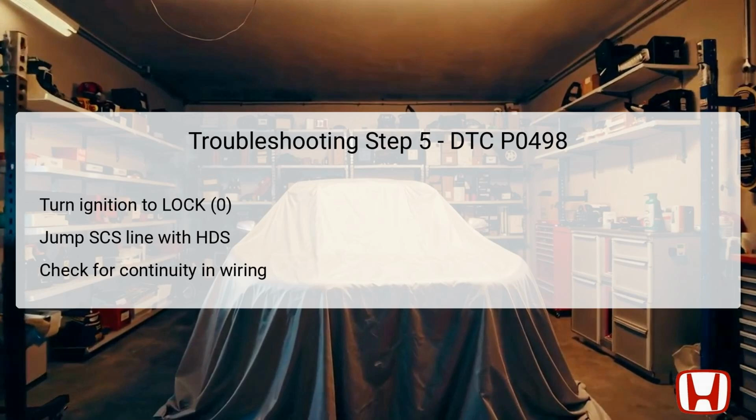This step is crucial to determine whether the wiring between the ECM and the vent shut valve has any shorts or faults. If continuity exists, it indicates that the wiring is intact. Else, you need to repair any detected shorts in the circuit for a proper diagnosis moving forward.